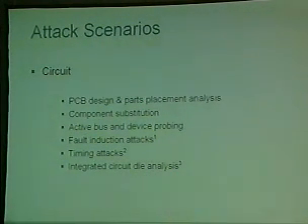The next two, fault induction attacks and timing attacks, have been talked about a lot with a lot of white papers recently. There are some references at the end of this presentation in the notes. These would be determined on a circuit level, but they could be applied to a system level, non-invasive attack, once the attacker can determine that they can be done. And the final one is integrated circuit die analysis. This is also a hot topic. This would involve delidding a device, possibly looking at the ROM layout or how the fuses are burned on the ROM or possibly in an FPGA.